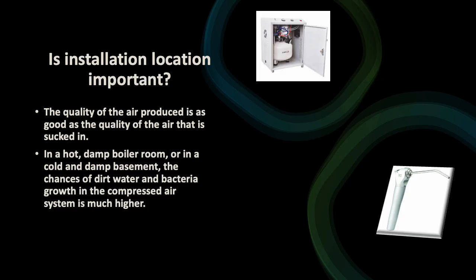We have another question. Is installation location important? Well, yes. The quality of the air produced is as good as the quality of the air that is sucked in. So, in a hot, damp boiler room or in a cold and damp basement, the chances of dirt, water, and bacterial growth in the compressed air system are much higher.